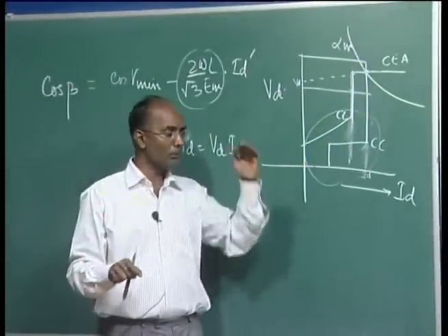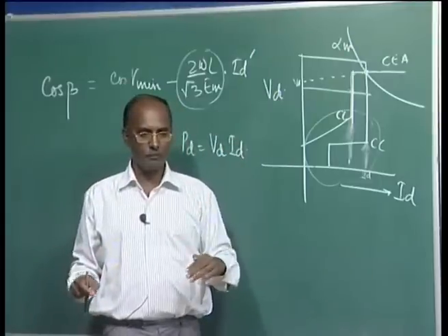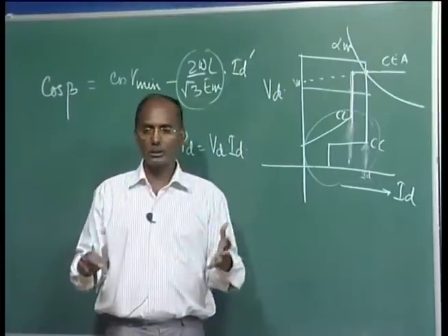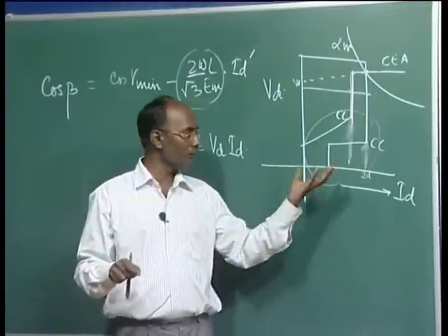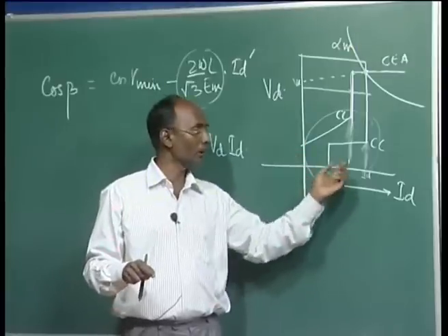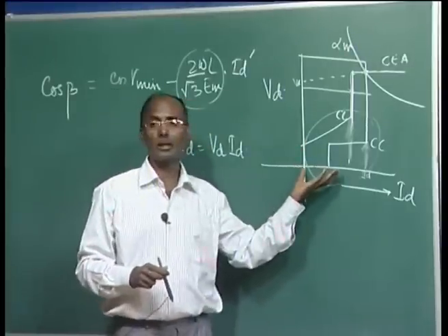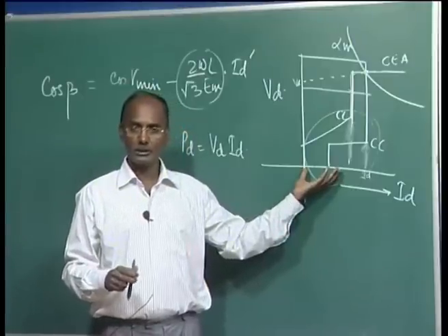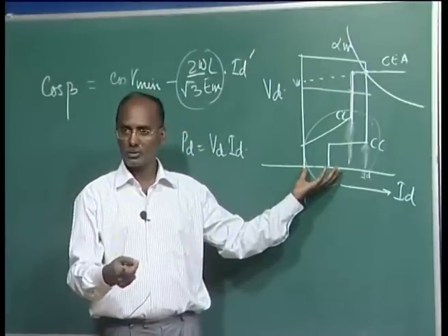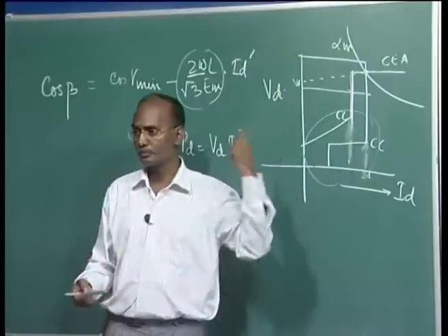We cannot maintain this if the voltage has gone down suddenly very low; your converter station will be highly stressed. So that is why we reduce power, and finally we operate in this zone, and this is called VDCOL, meaning voltage dependent current order limiter. Means the voltage has gone down, your current order is changed, and finally we operate in this zone.